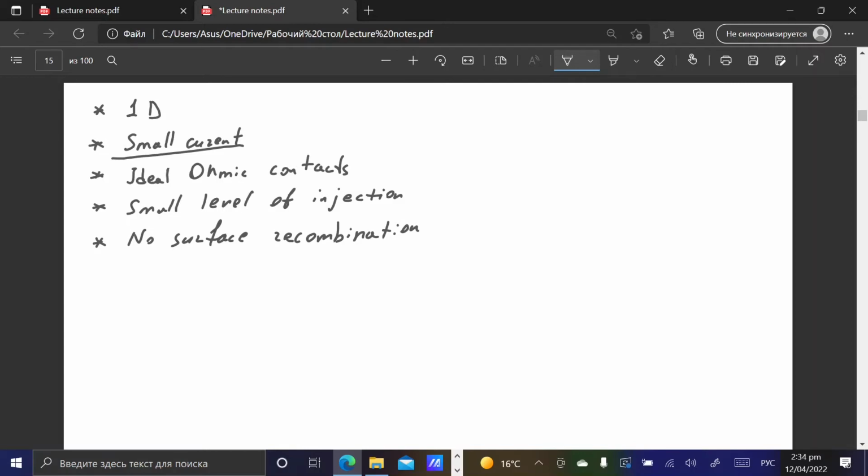And there are no generation-recombination processes of non-equilibrium charge carriers inside the depletion layer. That is something we partially considered when answering your question. I mentioned that if you have recombination via some deep trap in the depletion layer, then we need to know the concentration profile of charge carriers in the depletion region in order to know how they will recombine via this deep trap.